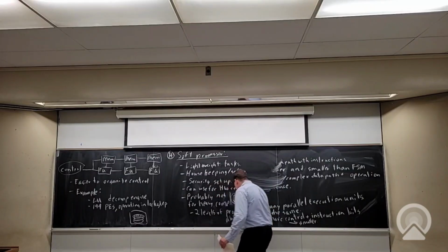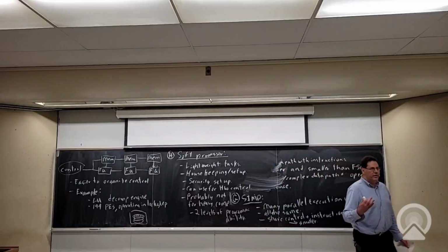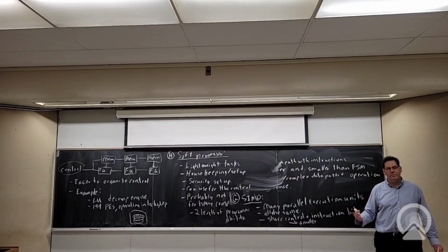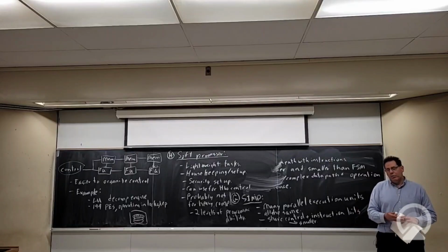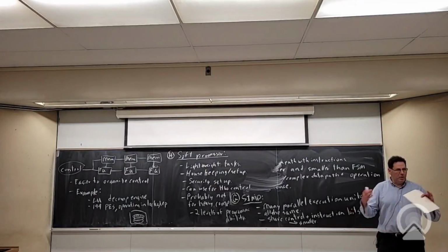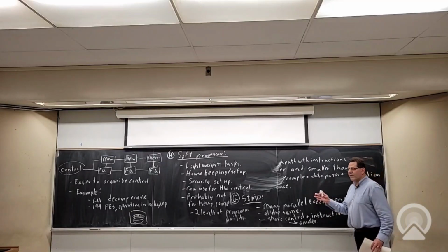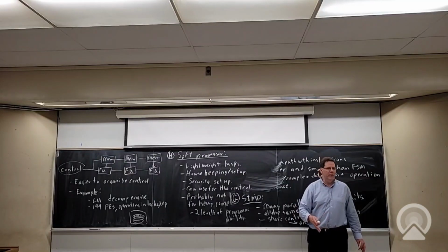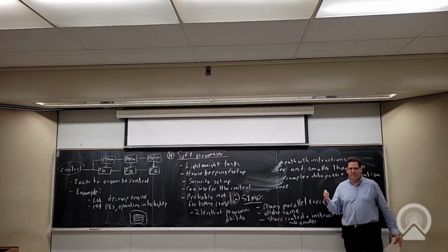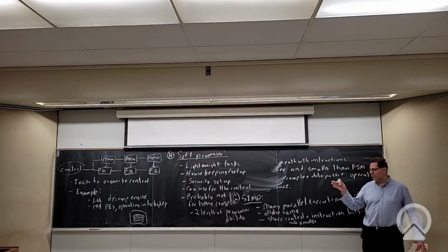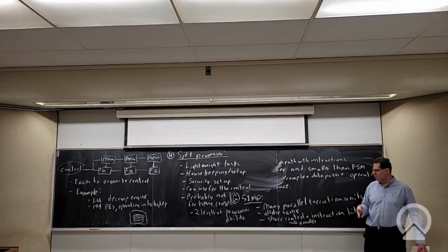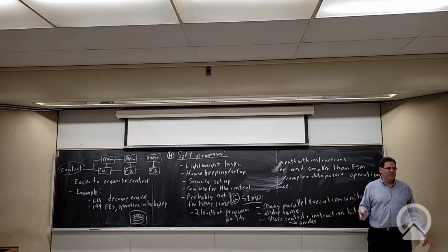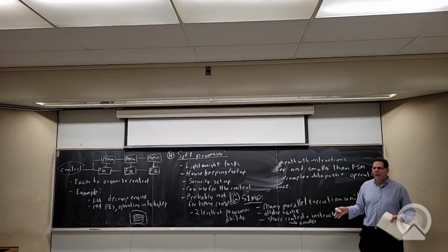Okay, so what do I mean by that? An FPGA gives up a lot versus an ASIC in terms of efficiency because it has programmable muxes, programmable logic blocks, etc., instead of just wiring things together, like taking the exact gates you want and wiring them together with metal. You're going to start getting into it in some of the papers next week, and then the week after we'll talk about it more. But that's not a small cost. It's on the order of magnitude, around 10x bigger.